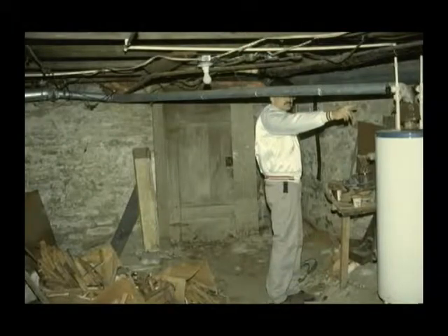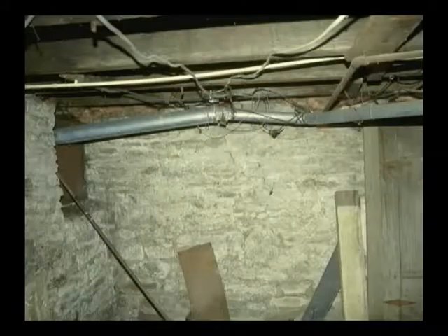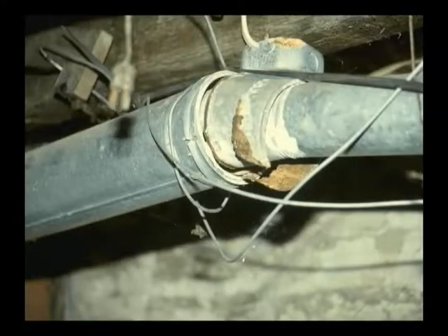Here's an example of a particularly bad water heater vent. It is long, has a low slope, and even a negative slope for a certain portion. The single wall pipe and the B vent weren't even totally connected. Virtually all of the combustion gases were venting into the basement.